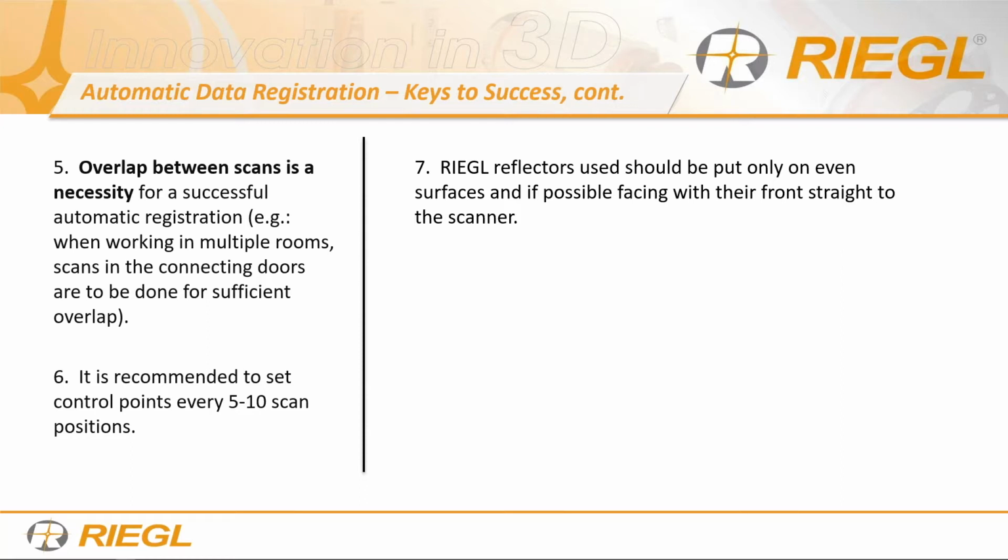But the cylindrical targets, we like them as well. We offer them as a standard target because you can see them from 360 degrees, great for road work. Use of RTK corrections and GNSS is recommended, but not mandatory. I always use GPS, whether you're getting correction from a VRS network or from a base station, or no correction at all. Our systems come with standard GPS, so always make use of GPS when it's available.